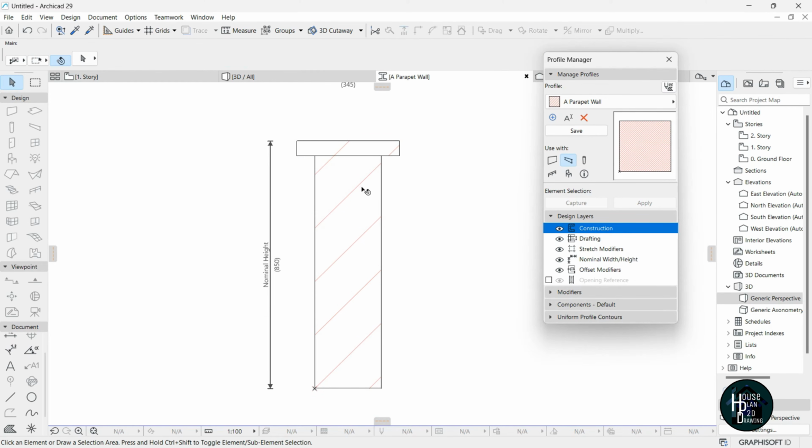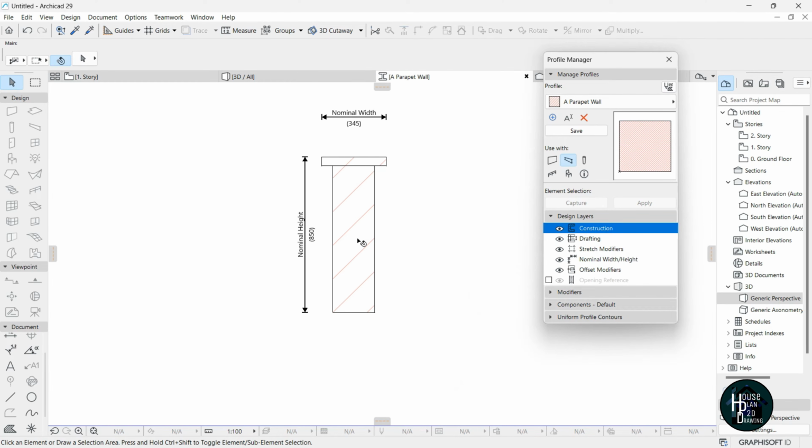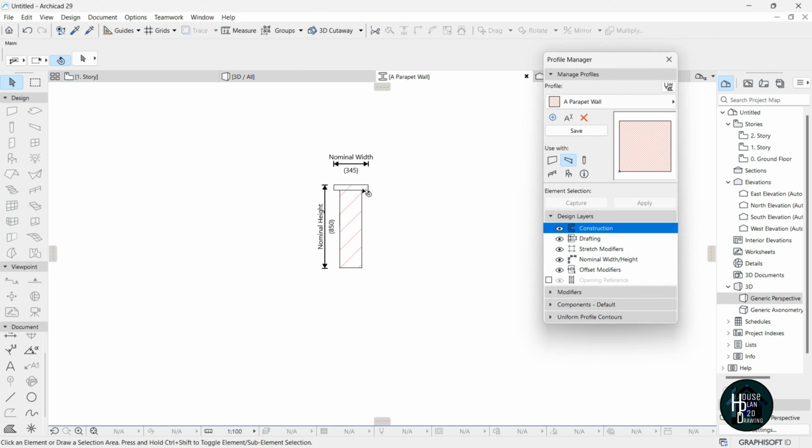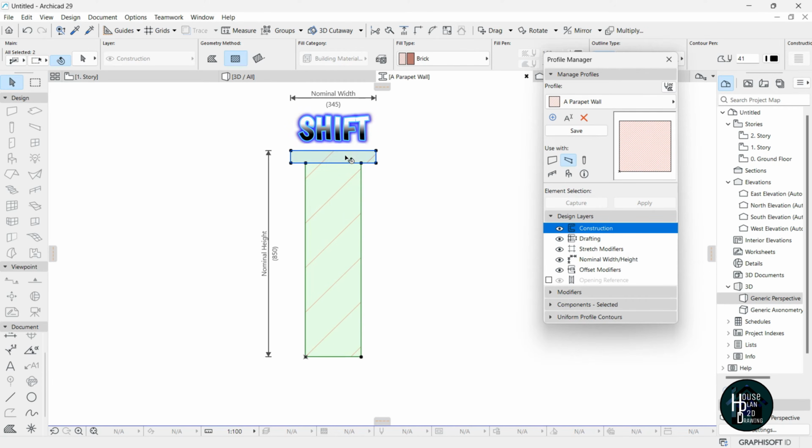Now just make sure that you're actually following the right thing. The measurements from here, if you take a quick measurement, click M on the keyboard, click this, this has to be 225. Okay, it's very important you guys, and the height has to be the same height. Now highlight everything we have here and untick this one here.